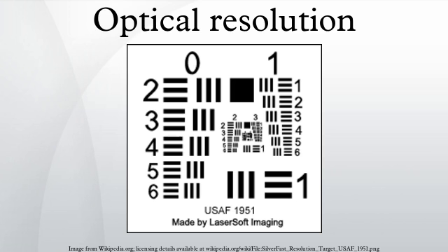Analog bandwidth effect on resolution. The spatial resolution of digital systems is fixed independently of the analog bandwidth because each pixel is digitized, transmitted, and stored as a discrete value. Digital cameras, recorders, and displays must be selected so that the resolution is identical from camera to display. However, in analog systems, the resolution of the camera, recorder, cabling, amplifiers, transmitters, receivers, and display may all be independent, and the overall system resolution is governed by the bandwidth of the lowest performing component.